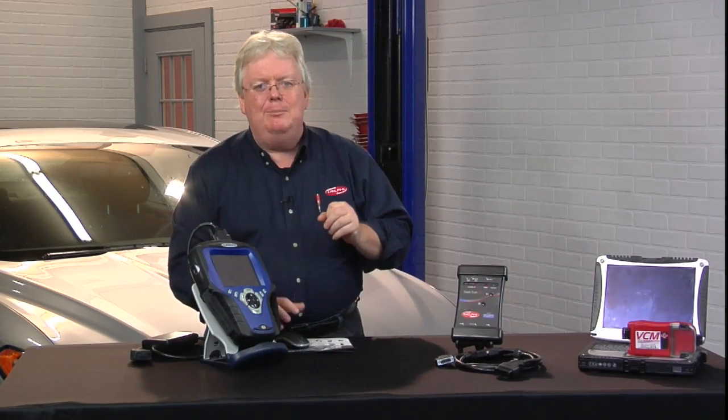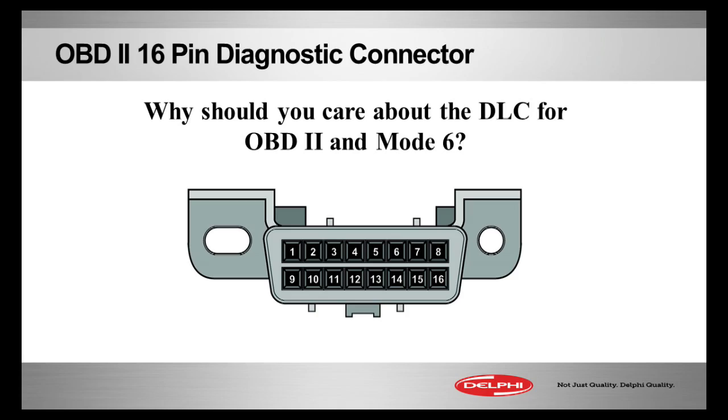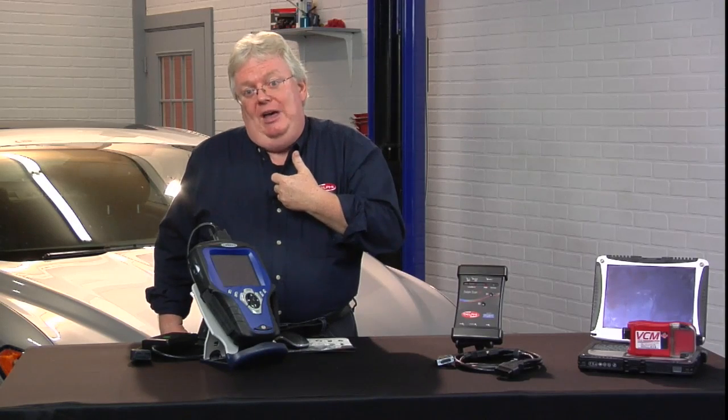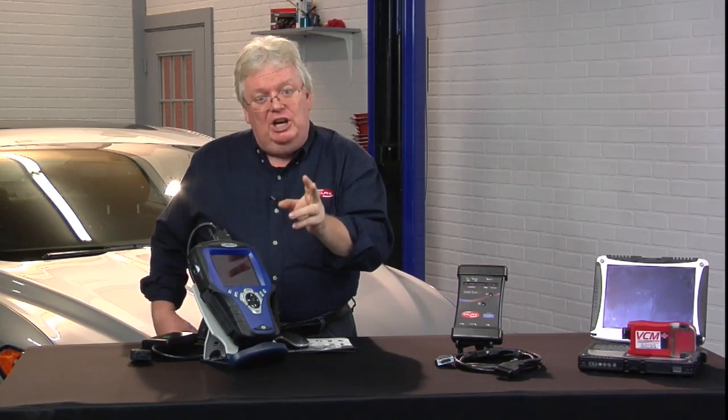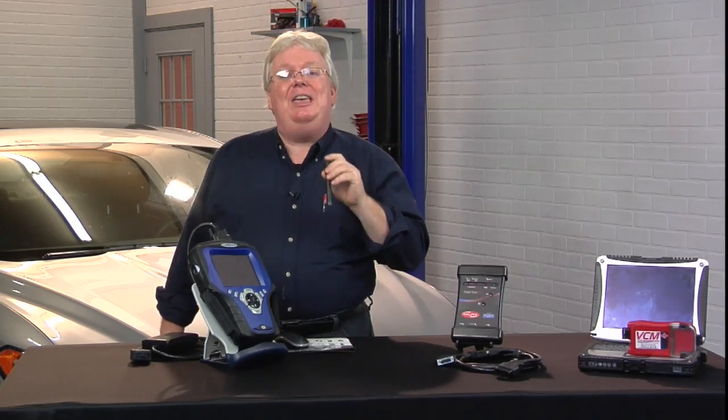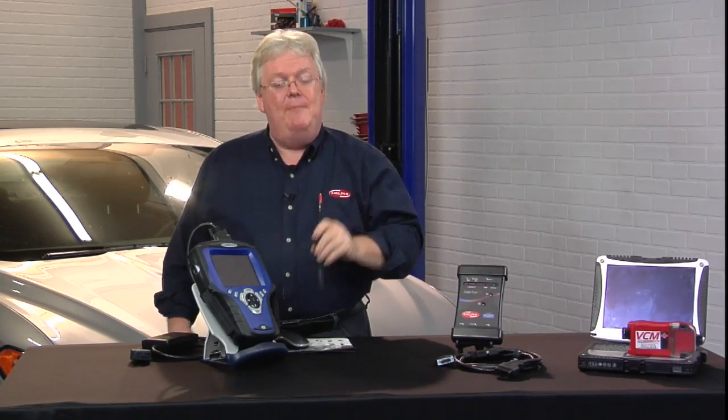An easy way to tell, if it's an 08 or newer, it has the CAN data bus, controller area network, and it will have terminals in pins 6 and 14, I should say cavities 6 and 14, of the 16-pin J1962 standard OBD II connector. Let's say it's an 04 Dodge Durango. Gee, I don't know off the top of my head if that has CAN, it's an early CAN user, or maybe it's an 05 Ford Fusion, and I don't know that one. Maybe you do. But the way to determine is just get down there under the dash with your little flashlight, take a look at the cavities in pins 6 and 14. If they're populated with terminals, both of them, you've got CAN.